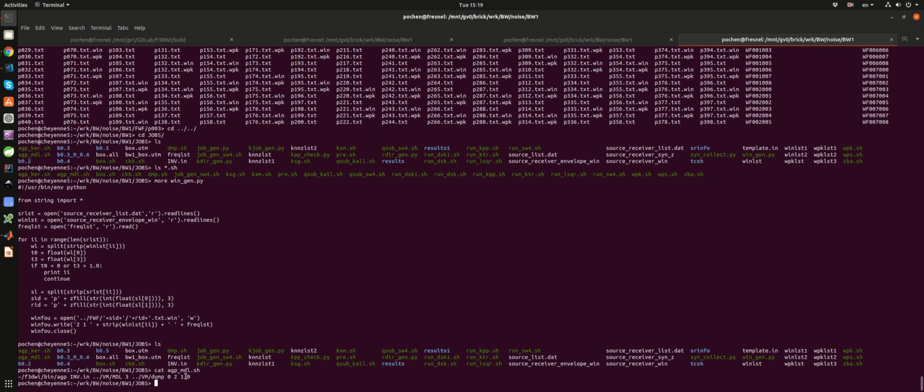But if you want to preserve the ordering of the recording grid points, then 210, right? So 2 means the z direction has to be the slowest, and 0 means x has to be the fastest, right? That way it's going to preserve the slow and fast directions in the binary output. And then this binary output can be read using MATLAB. If you want to make cross sections or plot map views, you can do that. It's not really that complicated.